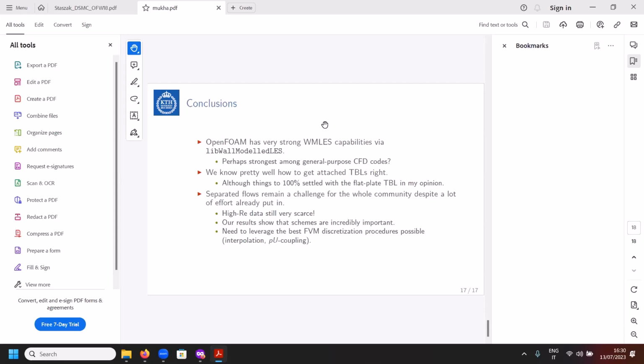The idea, I guess, is that the inner layer is so fast in its dynamics, the time scales are so small, that if you are at a high Reynolds number, then each of your cells is huge in y plus units and in y plus time units. Your time step is huge in plus time units. That justifies the fact that you can consider everything in the inner layer in an average sense. So whether one buys that or not is